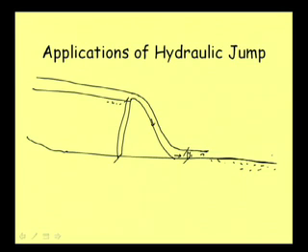Well, so what is expected is that we need to control this particular flow, and we should not allow this water to move much downstream. If possible we should try to form a hydraulic jump here where its energy will be dissipated. So, in this portion we need to form a hydraulic jump. If we can do so, its energy will be dissipated, and then whatever water is flowing downstream is flowing with less energy without causing any damage to the river bed.